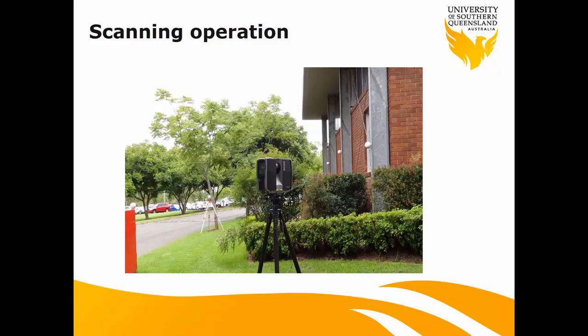What's the purpose of registration? We want to combine the laser scans that come from different laser scan stations. You will see this in more detail in the following slides. In order to get enough returning points from the target, you cannot put your target too far away from the laser scanner.